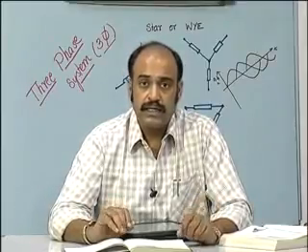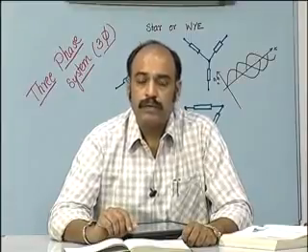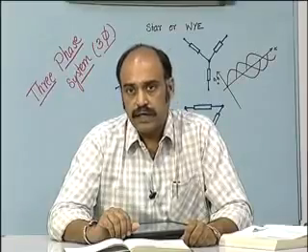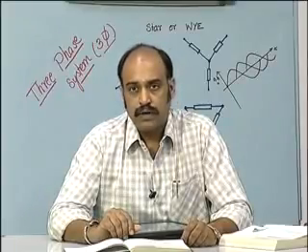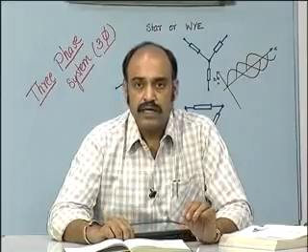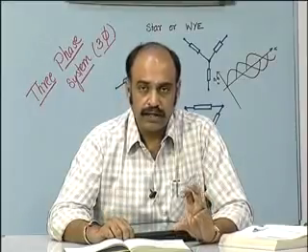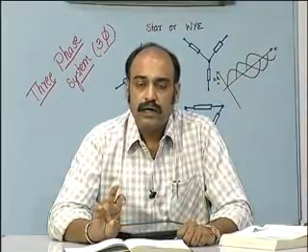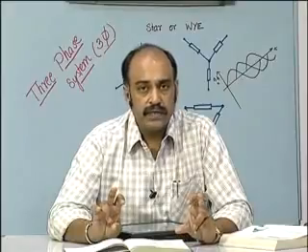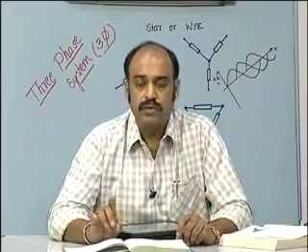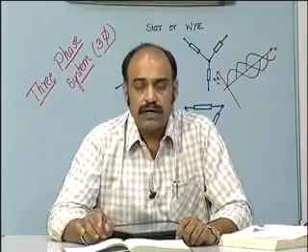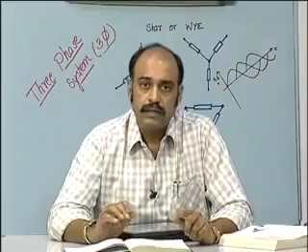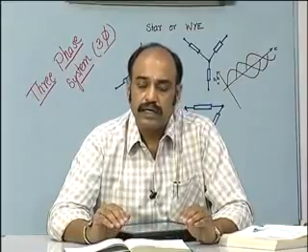In the case of the delta circuit, we discussed one important unbalanced load condition, and that is, in the extreme, if we had just one single resistor as a load. Then two of the lines will have currents in them, that is, one will have a forward current and one will have the return path current of the resistive load. The third line will not have any current and it will be just open.